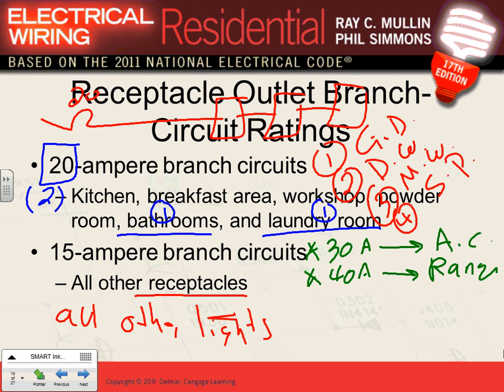Dryers. We have a dryer too. Another circuit, 30 amp. We have a dryer. Typically, this is what you're going to be doing in a kitchen, in a dwelling, dryer. These are all the branch circuits they're going to have in this apartment building, for every apartment, almost.